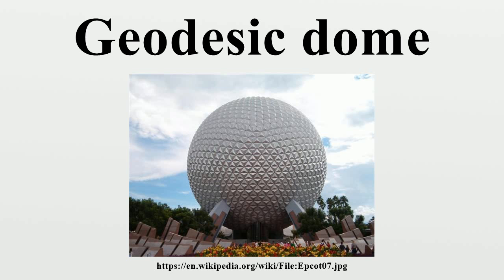Some concrete domes have been constructed from prefabricated, pre-stressed, steel-reinforced concrete panels that can be bolted into place. The bolts are within raised receptacles covered with little concrete caps to shed water. The triangles overlap to shed water. The triangles in this method can be molded in forms patterned in sand with wooden patterns, but the concrete triangles are usually so heavy that they must be placed with a crane.